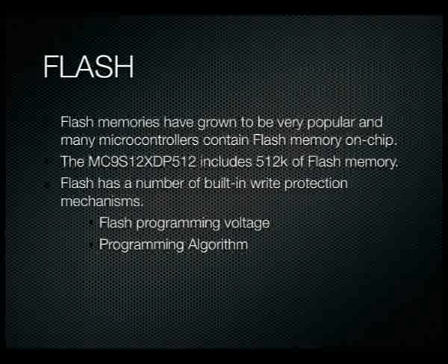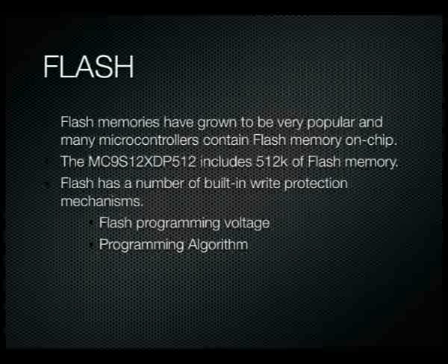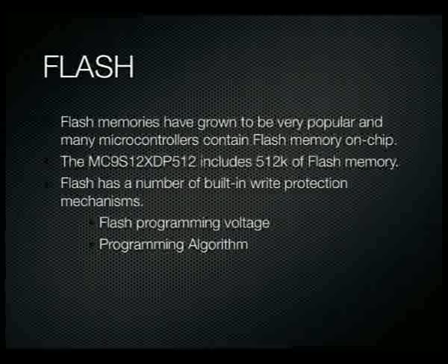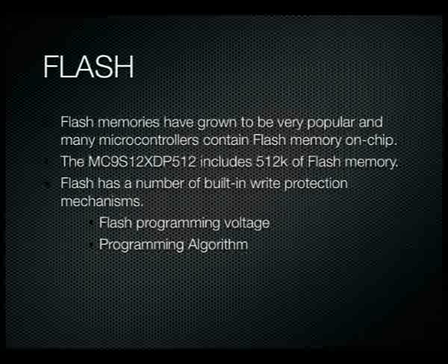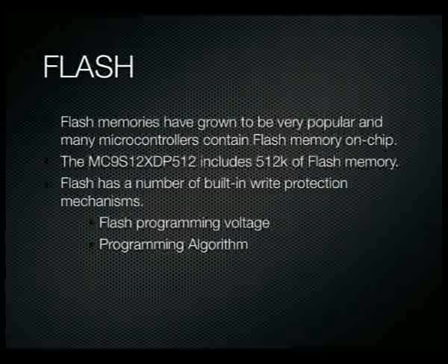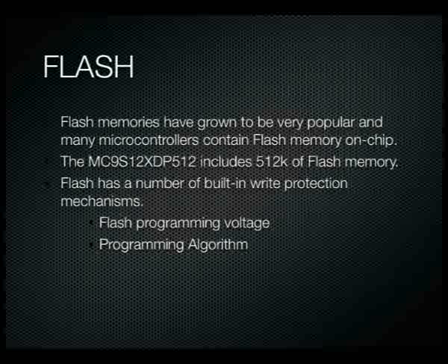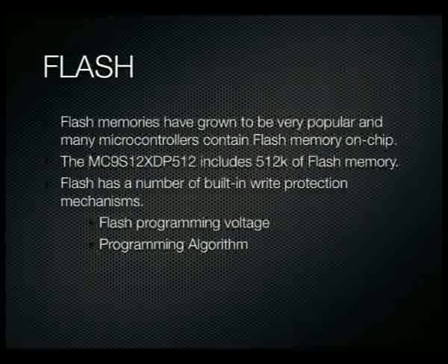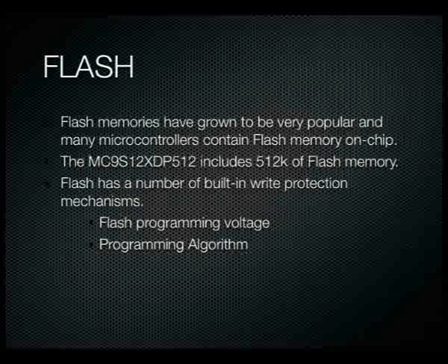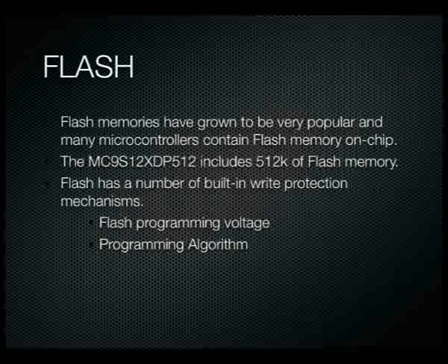So when it comes to flash technology, well, flash technology isn't as flexible. You might think we're going up levels of flexibility, but flash is not as flexible as EEPROM. With EEPROM, you can have byte erasable configurability, so you can erase a single byte, or you can even erase a single bit. So you've actually got very fine resolution when it comes to reprogramming. When it comes to flash, reprogramming actually requires you to do it a block at a time. It generally requires you to do about 512 bytes at a particular time. So you can't just erase and reprogram one byte. You've got to erase and reprogram a whole section of bytes at the same time.